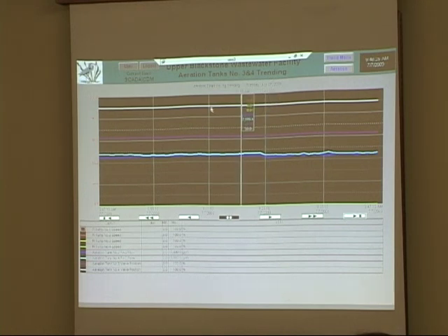If I just hover over a line, it'll tell me a lot about that. It'll say the aeration tank number 4 valve position was at 90. If for some reason I want to know the tag name, because say you're working with an instrument guy in the field, and you're having problems with a measurement, and you're trying to tell him at this time it keeps dropping out, and he'll say, what's the tag name? And all you're getting is the descriptions. If you just hover over that description, it actually even gives you the tag name, so you can tell somebody that is interested in the tag name, and it usually would be an instrument guy that's trying to go out and troubleshoot, here's the tag name.